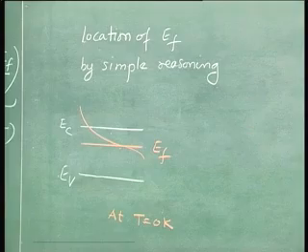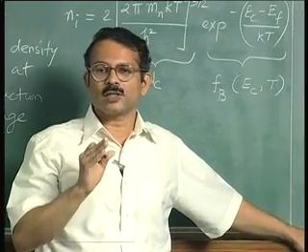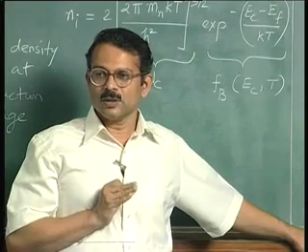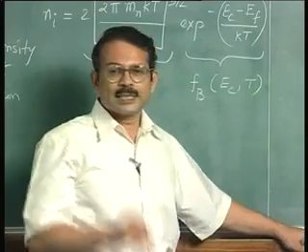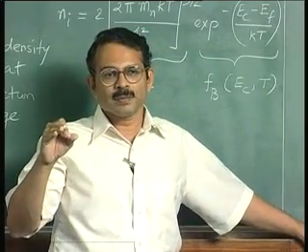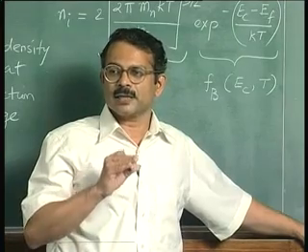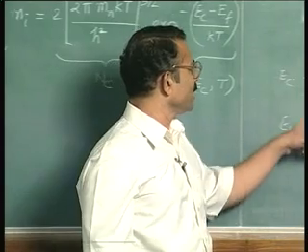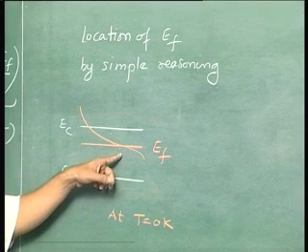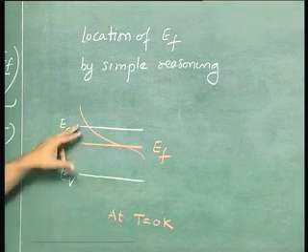Unoccupied states in the valence band indicate the hole concentration, and we have already said hole concentration is equal to electron concentration. Okay, we have explained why this is so. So translated into number of states, unoccupied states in the valence band are the holes. This should be equal to the occupied states in the conduction band in a pure semiconductor at any temperature. If these two turn out to be not equal for a certain choice of EF, then that choice of EF is not correct. Okay. Now how do we show that Pi will be less than Ni for this condition?